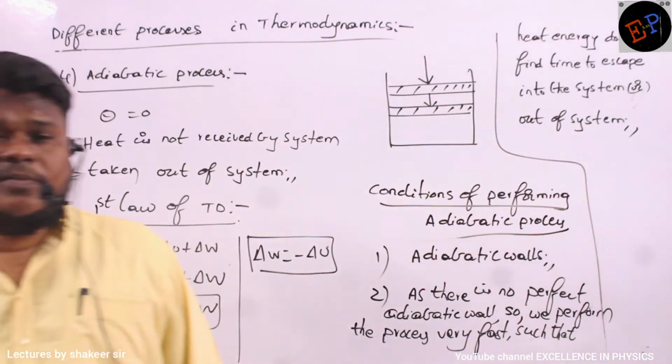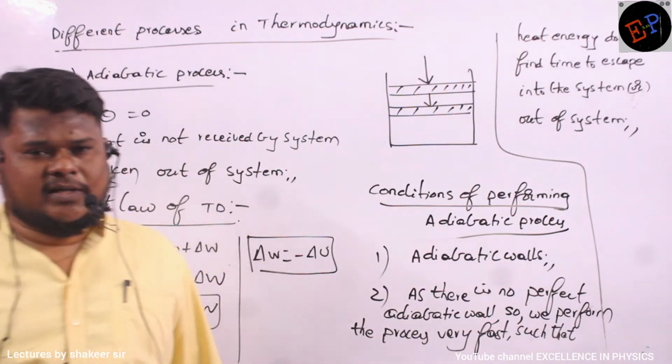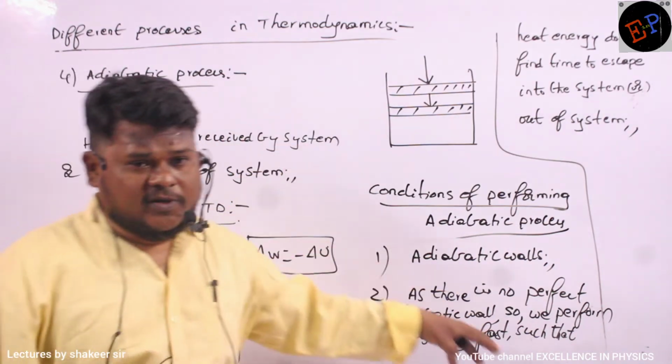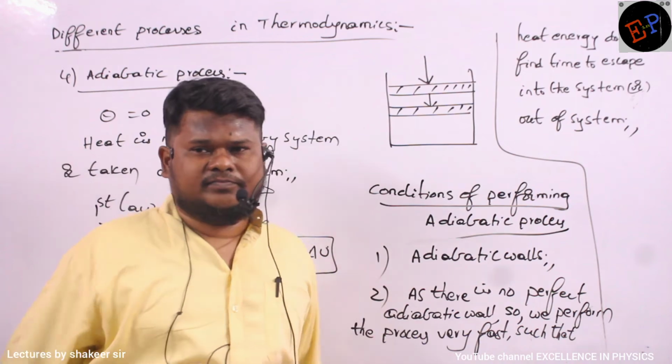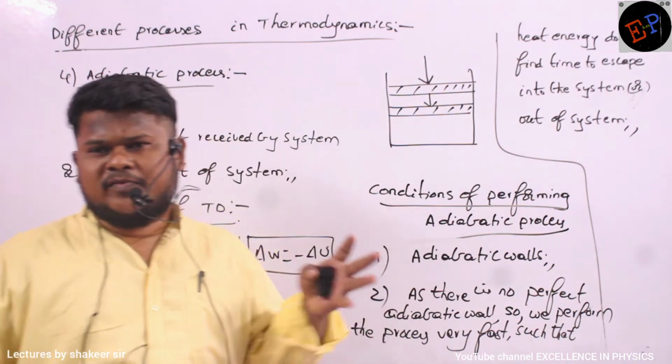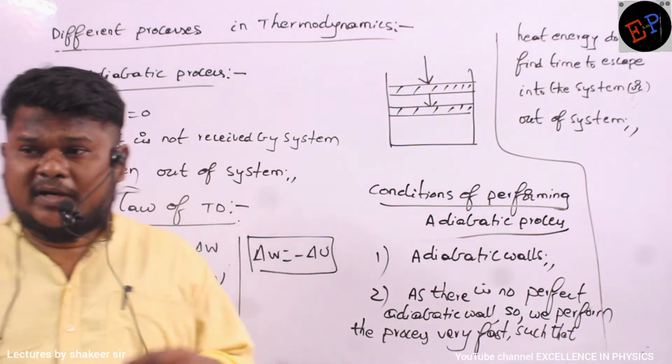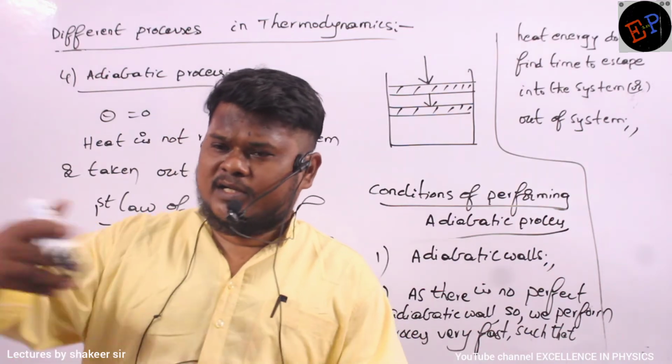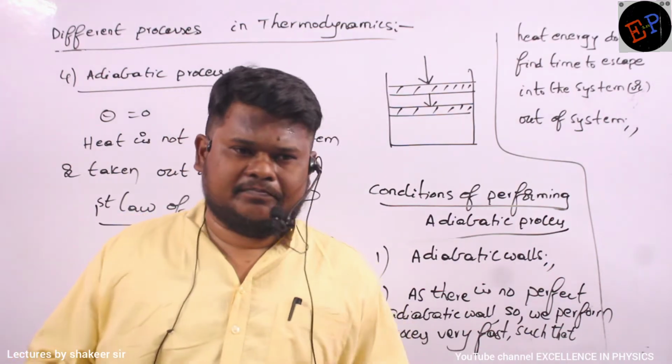Because there is no 100% perfect adiabatic wall, what we do is we perform the process suddenly. Within 0.1 seconds, we will do the process. So even if temperature increases, suddenly heat energy cannot flow into the surroundings. No? It takes some time.